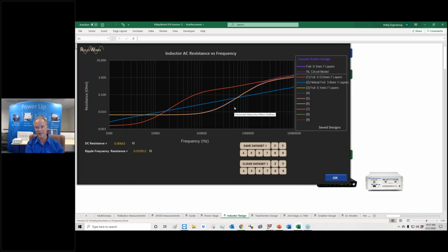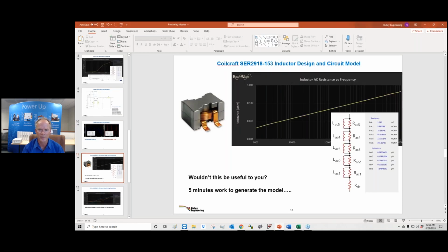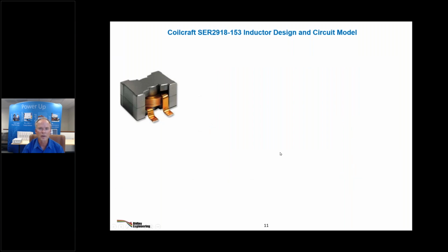There are really cheap inductors that give you the price that you want. There are good flat foil inductors, which I do recommend for these buck converters. As the buck converter ripple goes up and the AC portion of the waveform goes up, that can change to where you want to start thinking about different structures for the inductor. So this keeps on going. This is not so much research, this is applications. Every application is different. You learn how to wind with different structures and get these correct answers here. Okay, sorry if that was a bit confusing, but this is my point on this inductor for you.